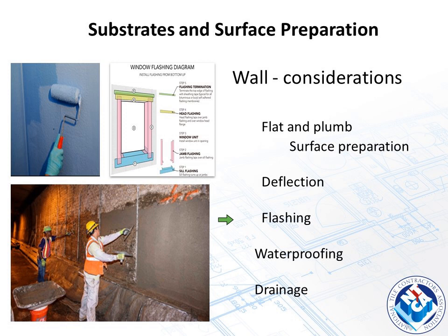Flashing is essential in all openings and is critical above tile installations. In some cases, I looked at a drawing today where tile is going to run right into an exterior insulation finish system. It needs to be weeped and a drip edge put out there so it can drain off the front, not into the wall system. Waterproofing is essential, and most important, be aware of the drainage, where it's going.